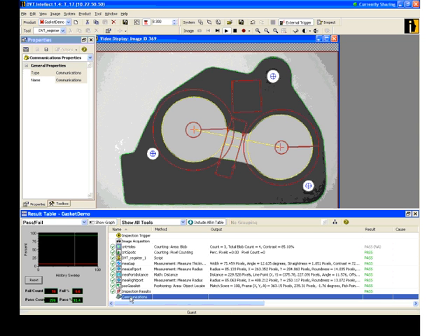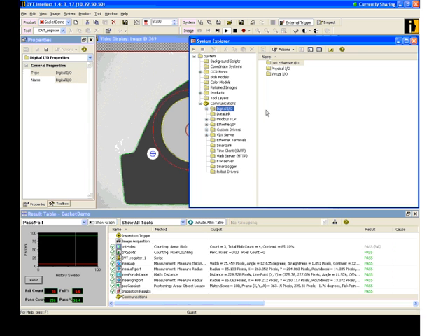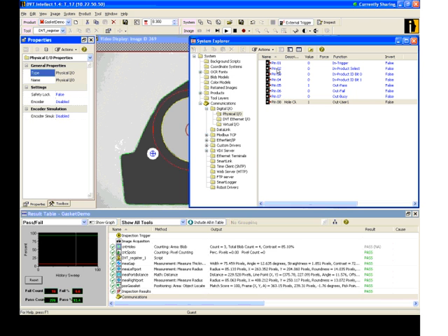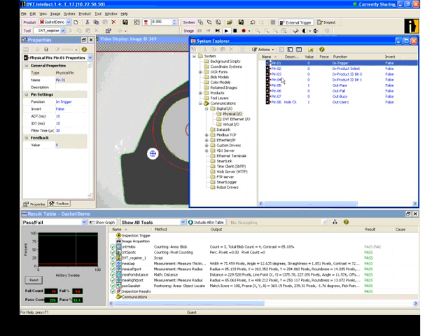So let's open up the communications screen. And here we have something called communications, digital I/O, the different methodologies for communicating outside of the camera. What we're going to be using is the digital I/O. There are 3 categories we'll be reviewing. One is going to be the physical I/O, the Ethernet I/O, and then one to view the I/Os is the virtual. So right now we're going to be working on the physical I/O, so we're going to go ahead and open that. And here are those 8 pins that I was talking about earlier. These are the configurable pins right here.